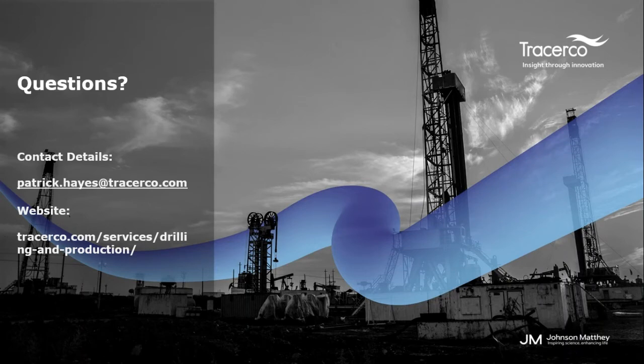We have a wide range of unique chemical tracers that can be applied, so we can fingerprint not only individual injection wells, but if we are able to isolate injection layers, then we can actually introduce a unique fingerprint into that layer and then measure for its presence in other producing wells, possibly in other layers, and determine whether crossflow is occurring and give some indication of the quantity of crossflow that's going on between those layers. Hopefully that's answered your question.